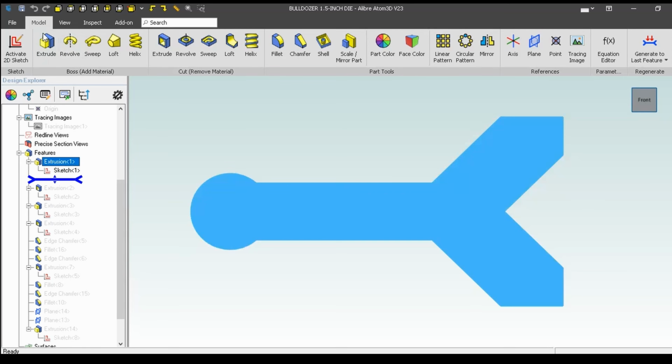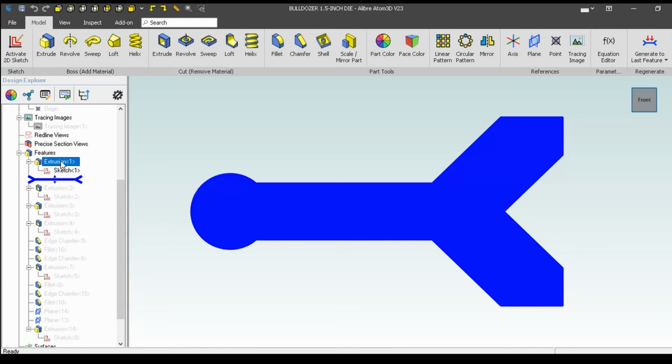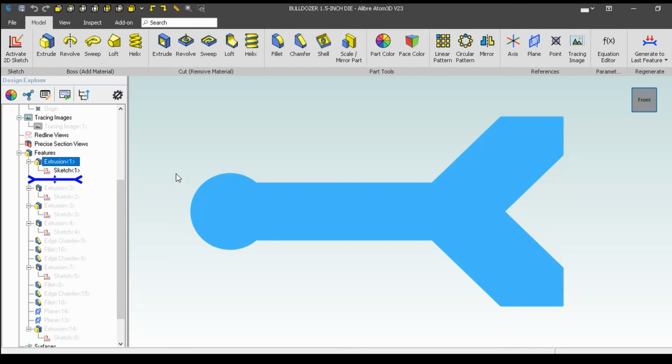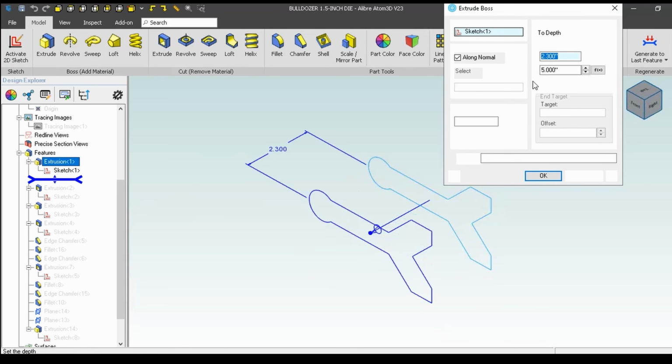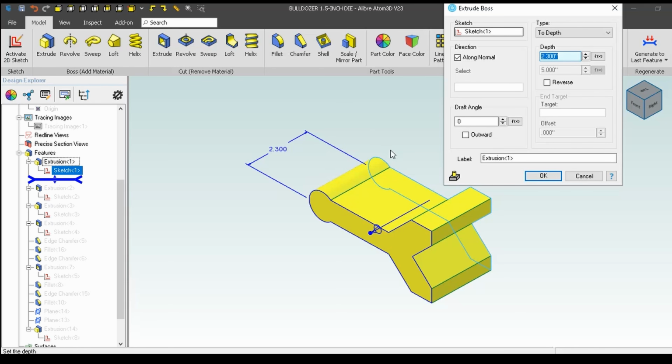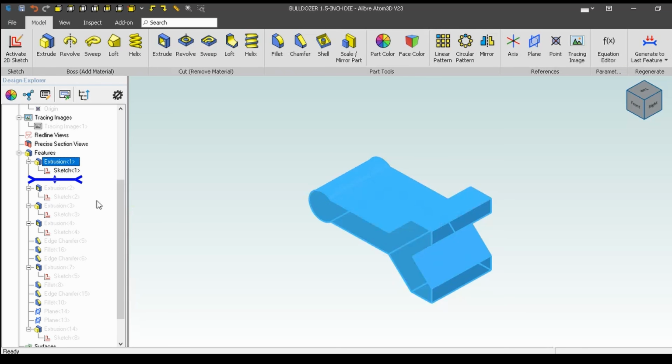and then you would go to the extrude, which was this command here. And I'm just going to edit that, so you'll see what the menu would look like. So to get that extrusion, I gave it a depth of 2.3 inches. You see here that image, from that sketch down in the light blue here, is going to go out 2.3 inches and make a solid block.